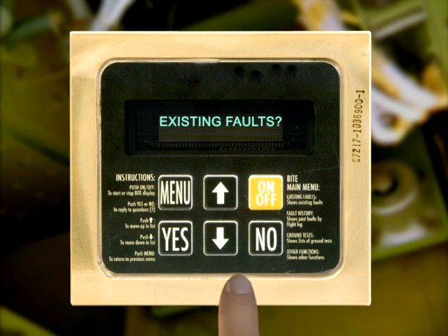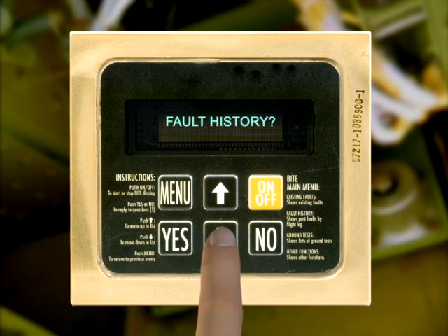You can cycle through a menu using the arrow keys. Pressing the down arrow key brings up the next item, Fault History. Fault History shows the details of previous faults that are in memory and specific information on when the faults occurred. Press the down arrow key again to get to Ground Tests. This item allows you to perform a series of tests on the nitrogen generation system. Finally, press the down arrow key one more time to get to the last item, Other Functions. This item can give specific information regarding the controller and airplane configuration.